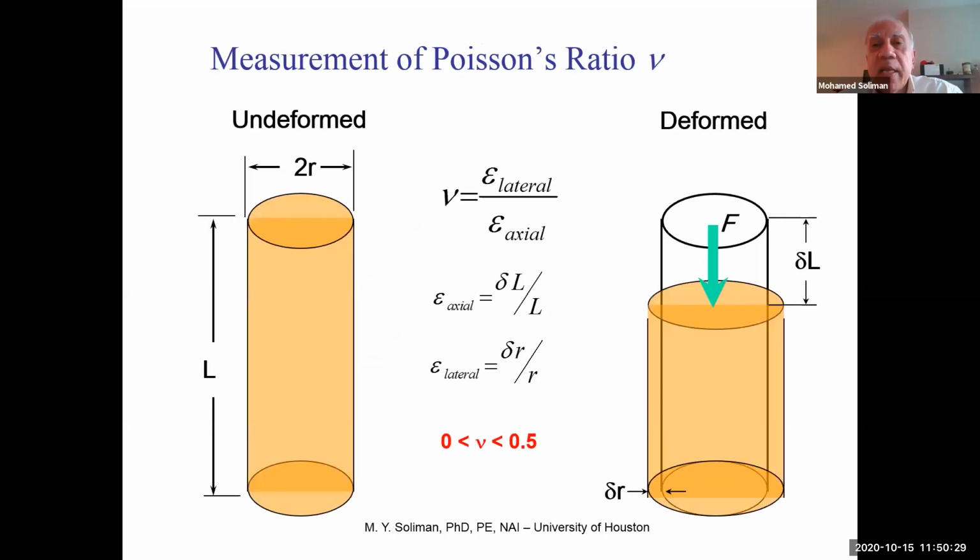Okay. Now, let's talk about Poisson's ratio, then we'll give a table. If I'm running this experiment again and applying this force, not only am I measuring the change in strain, I'm getting that this rock is getting wider. So there is axial strain, which is delta L over L, but there's also lateral strain, which is the change in radius divided by radius, or you can call it change of diameter divided by diameter.